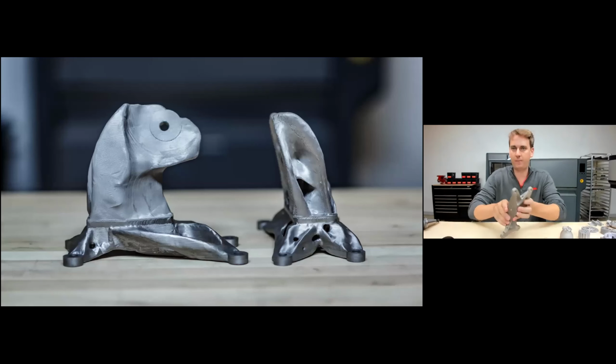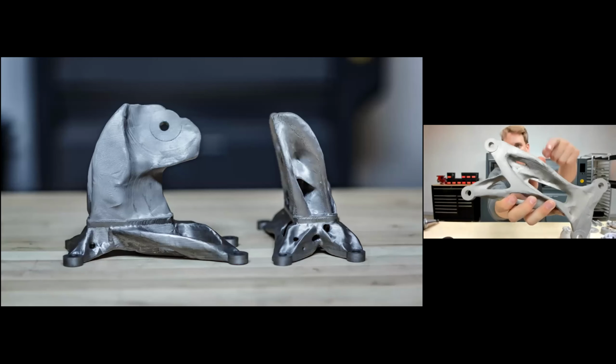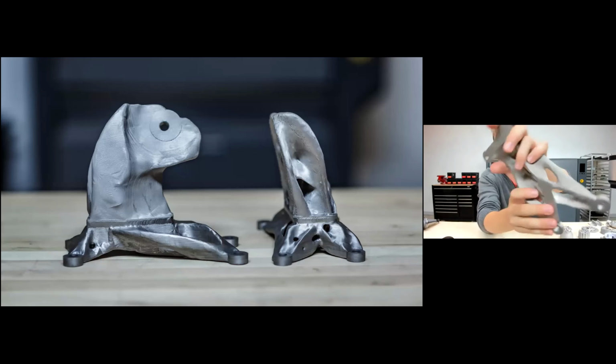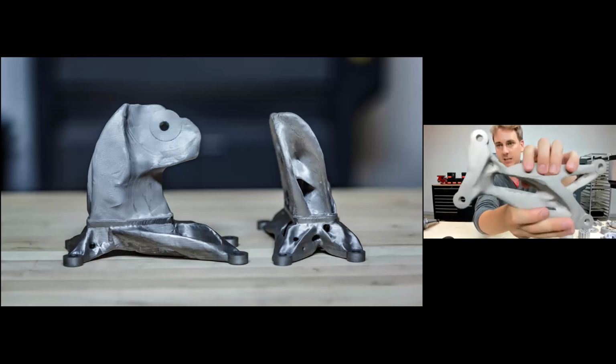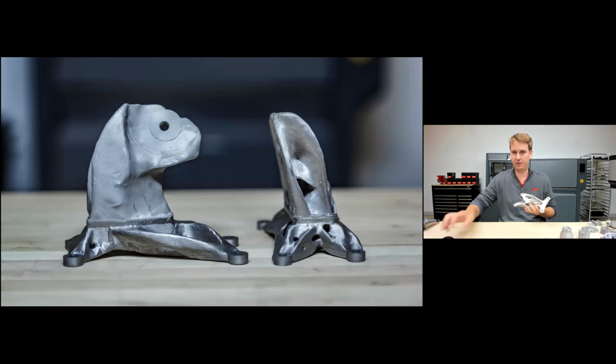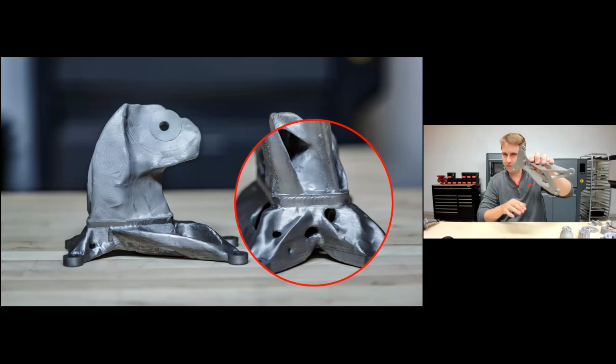And you can see the final parts here. I'll pull this up to the camera. It's a little bit too big to fit in my overhead scope, but you can see that natural webbing, the very organic shape of this feature that would be extremely expensive and very difficult to machine, yet it's no problem just to print these components. This part was actually too big to fit on the volume of the Studio system, so it was printed in two components, the base plate that I have here, and then the top plate, and then simply welded together.